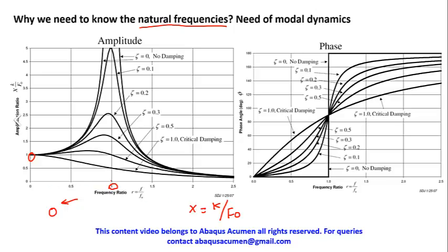And then specifically when you cross this point, you see the response where the loading frequency is higher than the natural frequency, then the response is not even a static response, it is much lower than a static response.